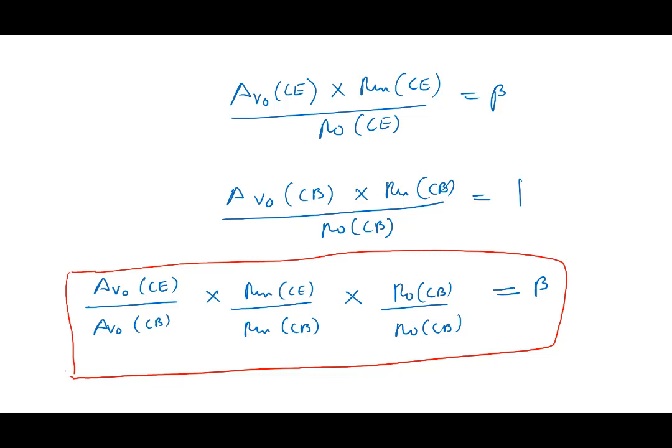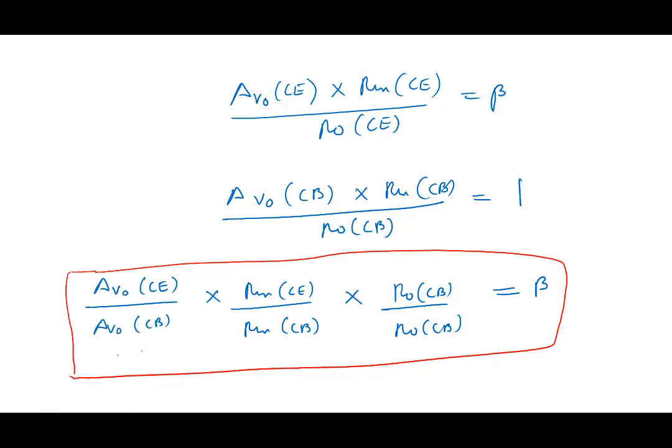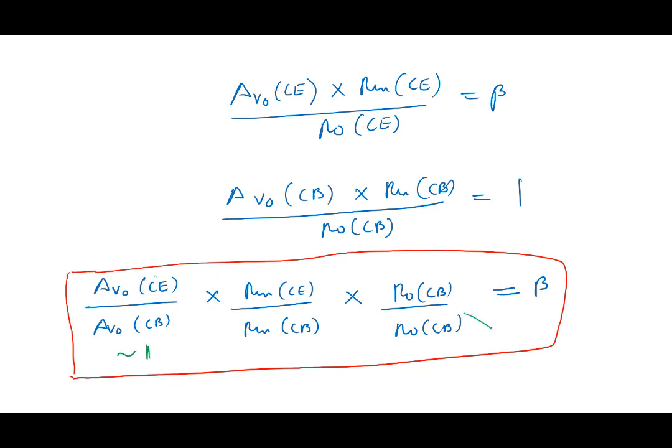There are several ways of looking at this amplifier, right? The traditional way of looking upon this comparison of common emitter versus common base is, well, if you take this ratio 1, both give you the same gain. Both give you 1. Then what can you say? Suppose I designed both the amplifiers with the same gain and with the same output resistance. Then what can we say as a comparison between them?